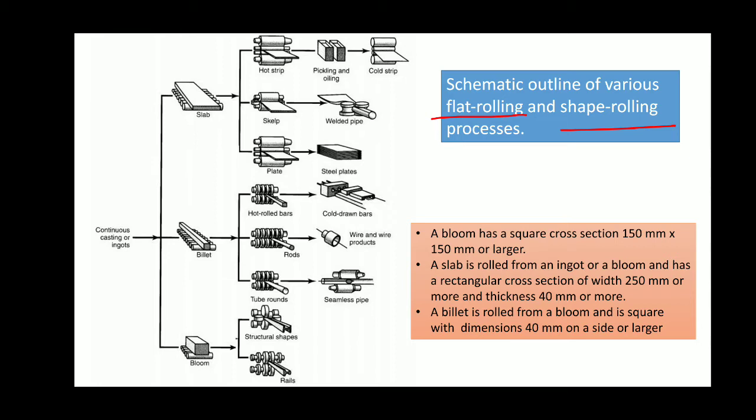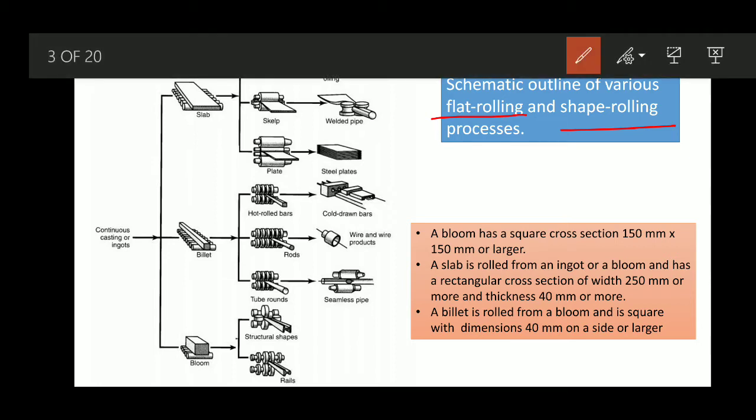Here you can see the rolls are kind of flat. So this is the flat rolling process. There is no contour made on the roller. But here, or here, as well as here, you can see some contours being made on the roller. That means we can have a gap between the rollers wherever needed, so that way we can have the corresponding shape on that final part.